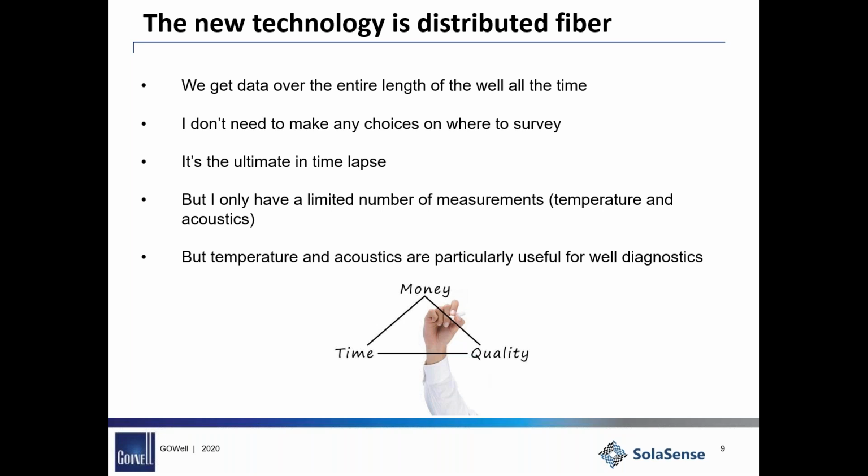And then likewise, there's always the hydraulic conduit way of deploying the fibre, where you've got a turnaround sub and a 1/4-inch control line going all the way down, that you can blow the fibre down and back up again. So it's a double-ended system. Those are in existence and have been used quite successfully. But that's quite an expense, both in terms of rig time and capital to install that stuff.